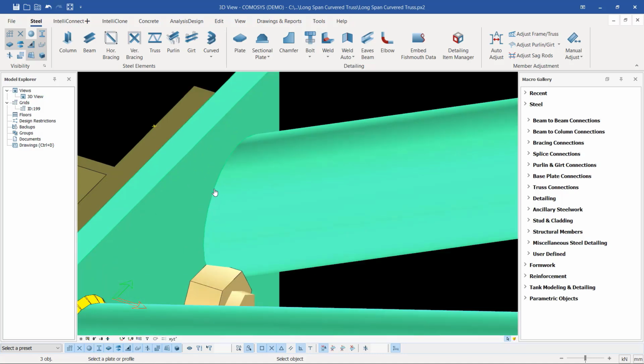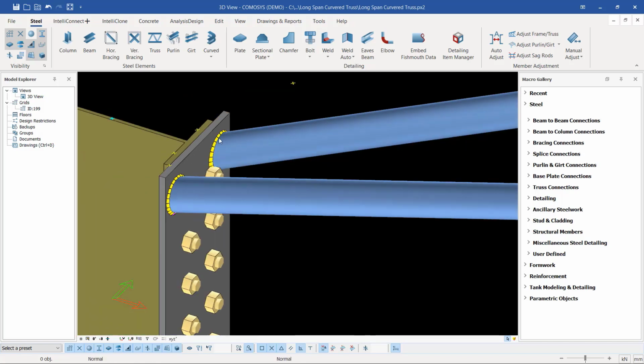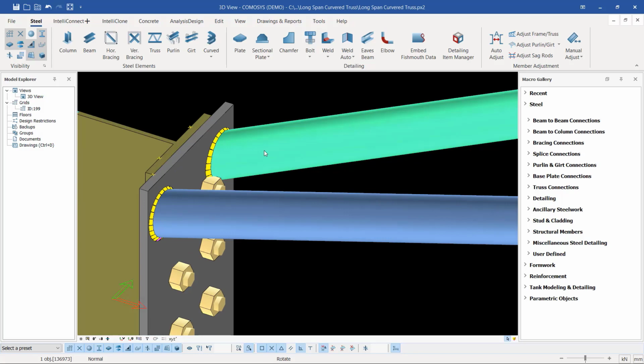I want to weld it to. I'll select on that spot and the welding has been created. You can see that welding. And to confirm that, I'll select that member and right click and come to select assembly. You can see the bolts are getting selected, which means this is a full assembly and this will be carried to site as it is. So if I click on empty screen there, you can see that get deselected.